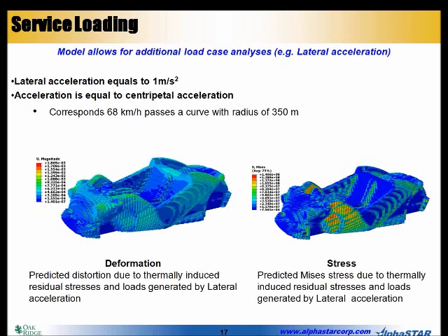The residual stresses due to the production process can also be used in a post-analysis step where you can include some service loadings. In this case, we have just added, to show that we can add different loading cases after the production has been finished, some lateral accelerations, which is representative of a car going through a curve. And we can show the deformations and the stresses, which are the stresses due to the acceleration plus the residual stresses that are already in the material due to the production process and the thermal loading of that.